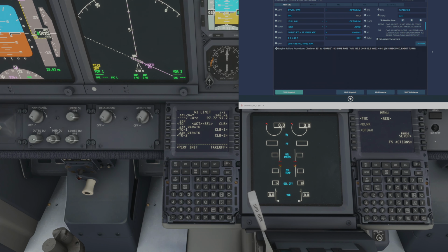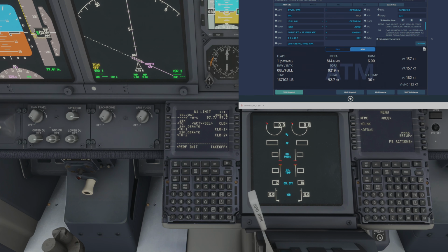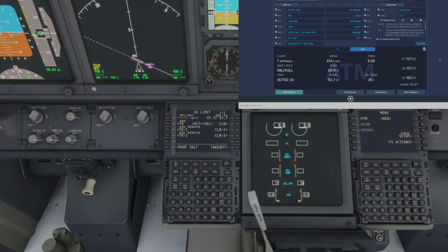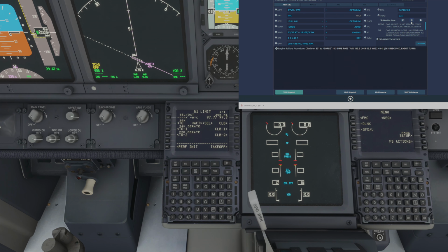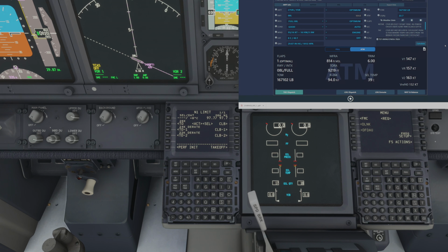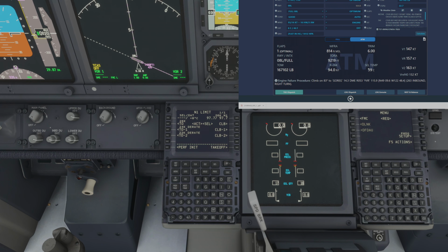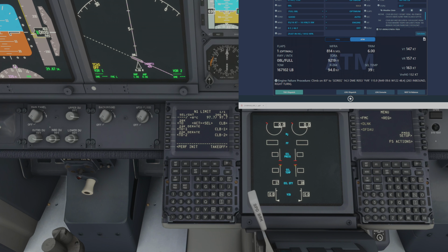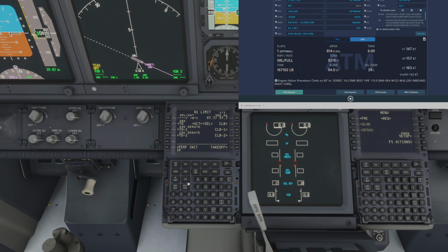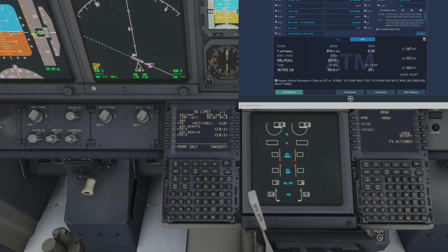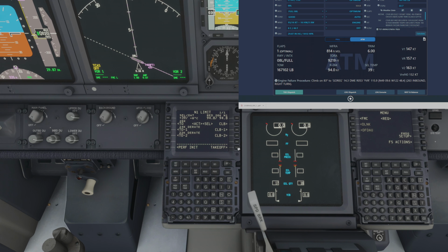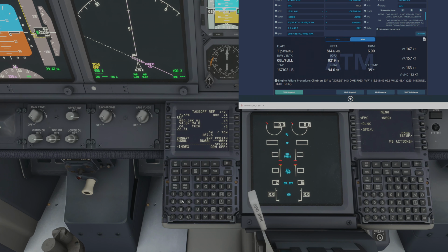And we're gonna go with engine. All right, so we have light rain, fuel at 3,300, overcast 73. Alright, so we do have 26K assumed temperature here, so 26K, and we'll put in 39. So 94.8. Once you turn on the engine anti-ice, I'll drop down to 94, and we'll go in for takeoff,